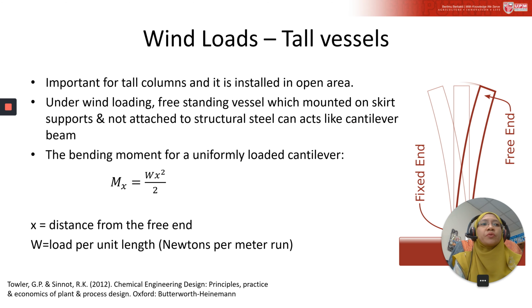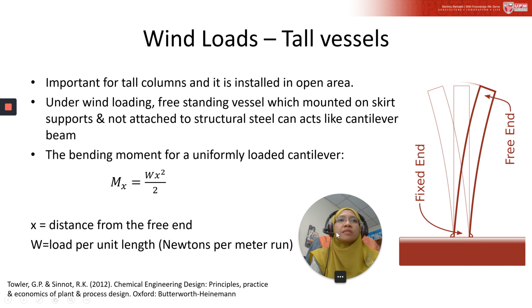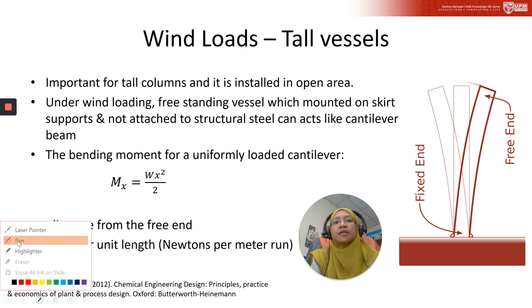Then for wind loads, it is important for you to know that a tall vessel installed in an open area outside of the premise, under wind loading, especially a freestanding vessel mounted on the skirt support only and not attached to structural steel, can act like a cantilever beam.